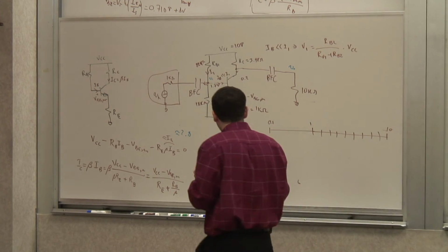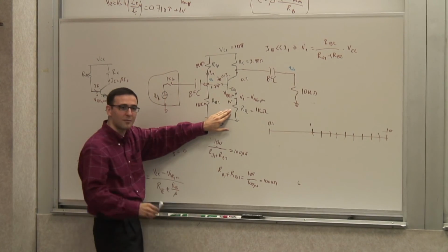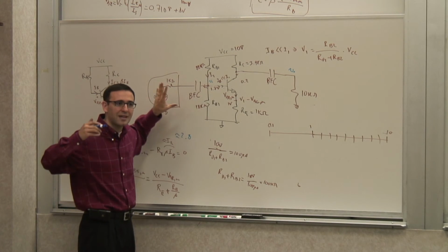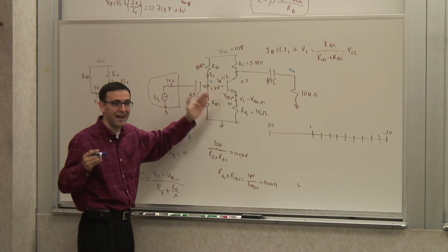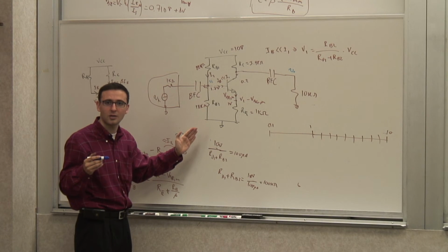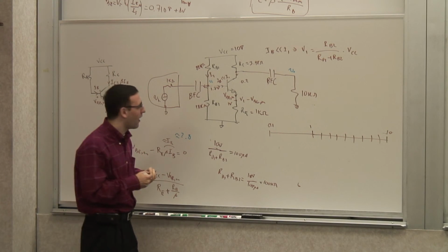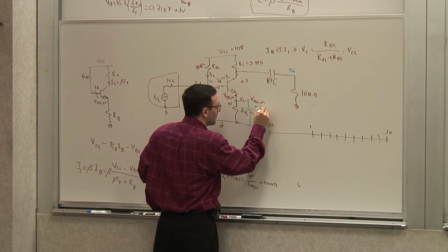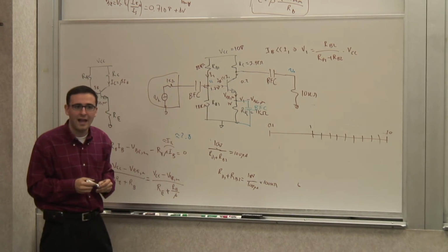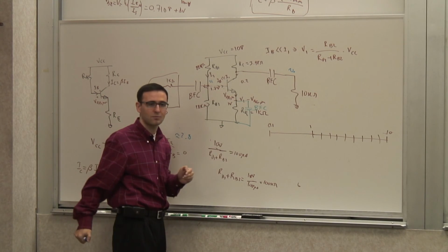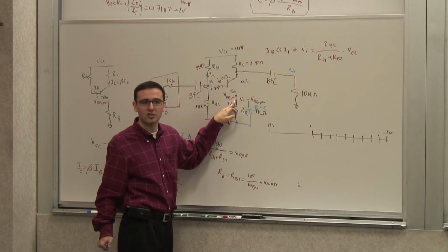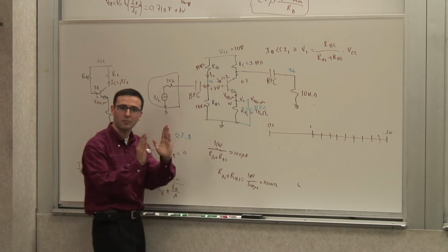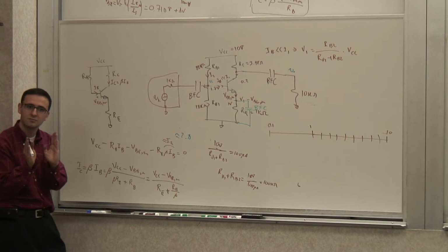Okay, yeah. So I want this resistor to be there from a DC perspective because it helped me with my bias. It got rid of my beta. But from an AC perspective, I don't want this here at all. It's just a horrible thing to have. So one way to get rid of it from an AC perspective is just to put another big fat capacitor here. And from an AC perspective, you shunt it. It just basically becomes a short. It becomes a non-degenerate common emitter amplifier. But from a DC perspective, it's there and it makes sure that my bias is established in a stable way.